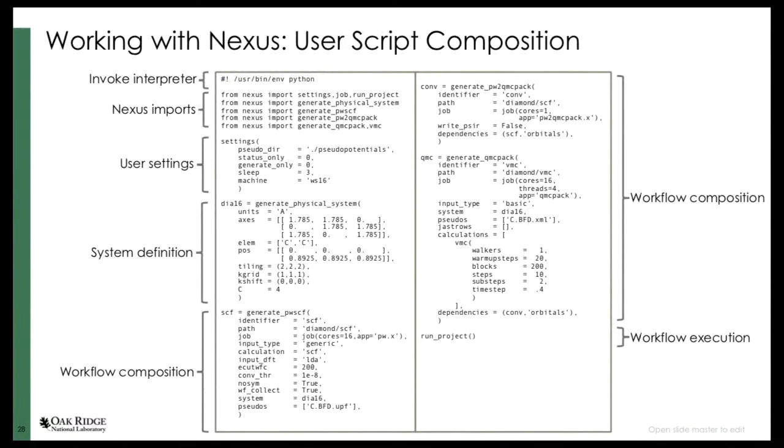These examples you're putting in like position angstroms. I mean, whatever you want to put into the last one. Oh, yes. Or space group equal points. Okay, so I probably should have spent a little more time on how you specify the system because there are many more options than what I showed here. That's probably more convenient much of the time. For example, instead of specifying all the coordinates yourself, you can point to a POSCAR file or an XSF file or even a CIF file and start from there, and it will just load in the coordinates for you. For a lot of people, that will be the easiest way to work rather than rewriting it all in this type of format.